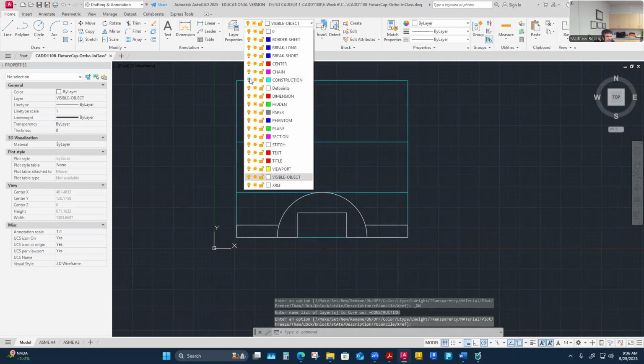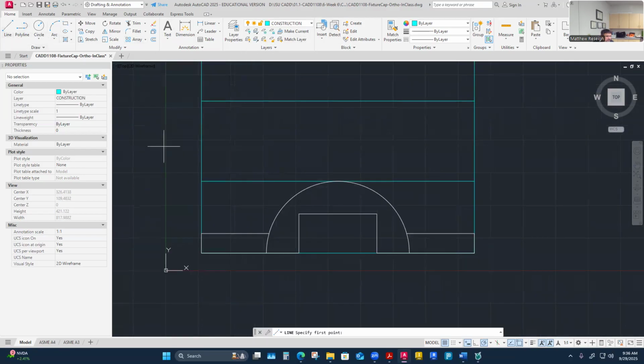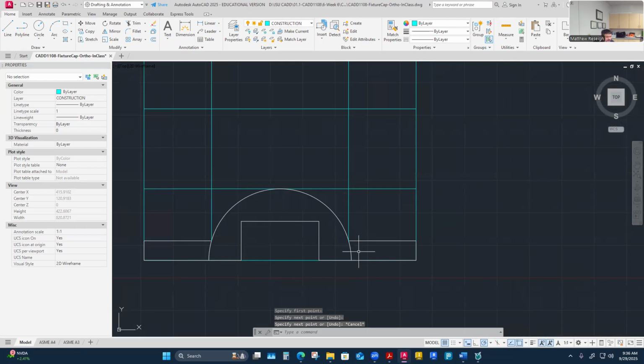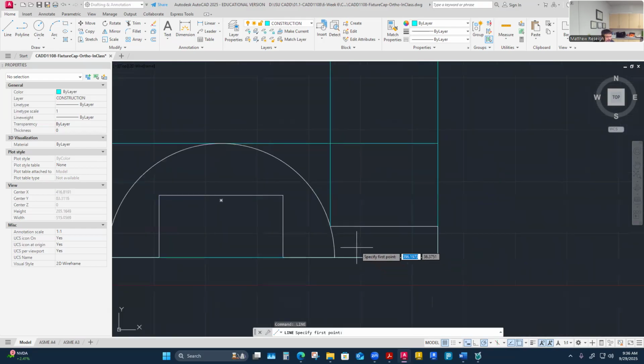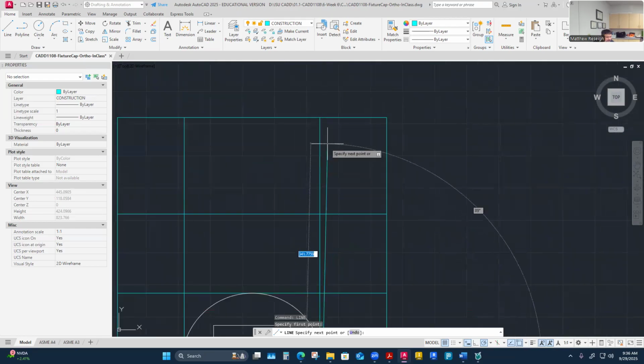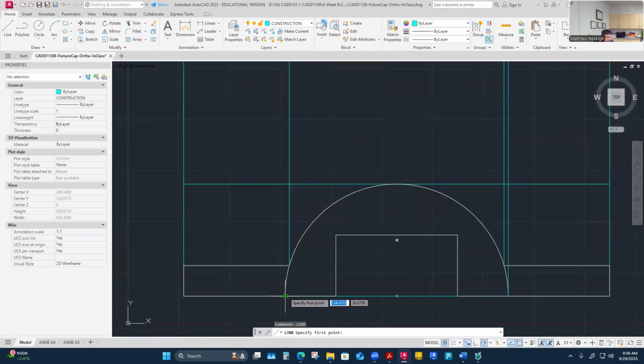Let's project up. I'm just projecting up those. That's the edge of the ear, but there's also this one that is really the diameter right here. This is round and this is the rectangular view, this diameter. And so these two lines are close together. I'll project them both up. I just want to keep track of both of them. They're really close together, but they are two different projections.